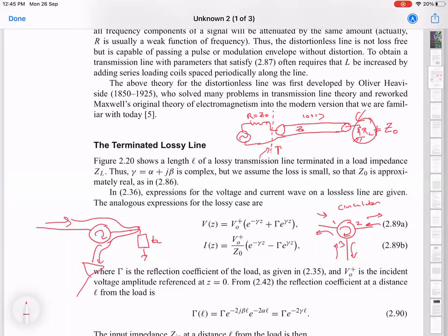So in practice, there are cutoffs and things like that. But this device doesn't do any frequency selection outside of the band of the operation. Now, this was something I was not going to go into now, but this kind of a circulator device actually only works over a narrow range of frequencies, just like impedance transformers and other things, because this also relies on a resonance condition, and usually they have octave bands. So the one we typically use in our experiments is 4 to 8 gigahertz. So outside of that band, it doesn't do this operation.